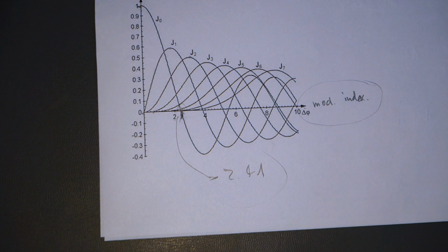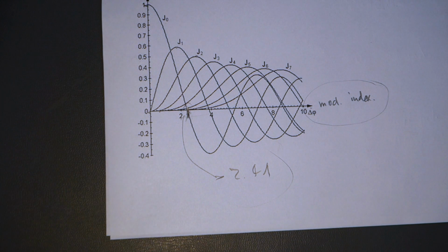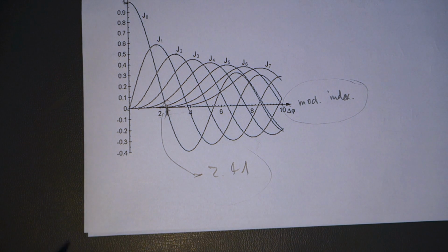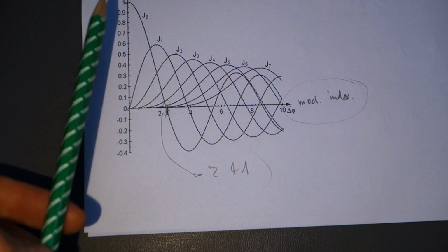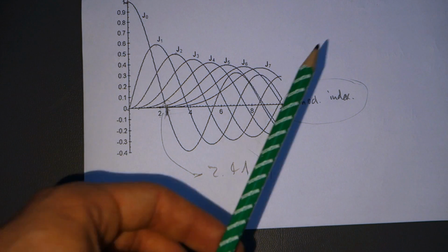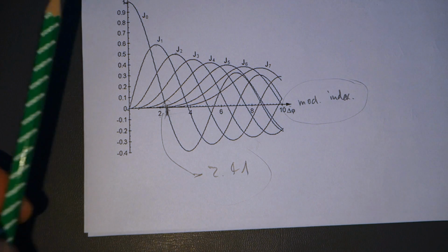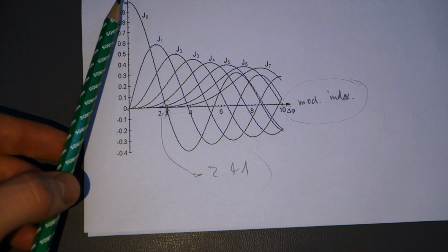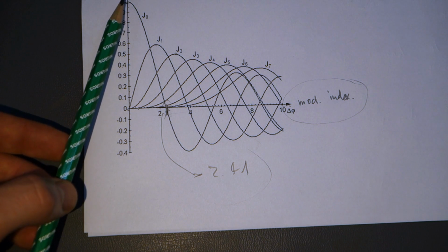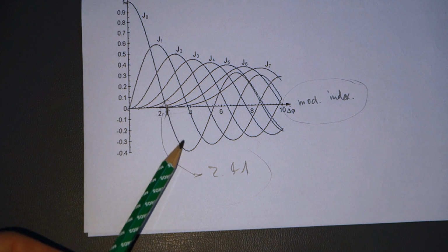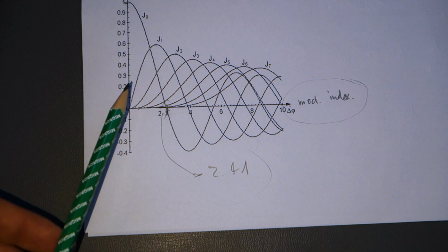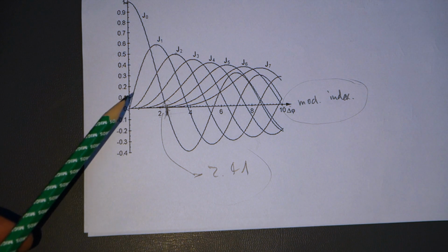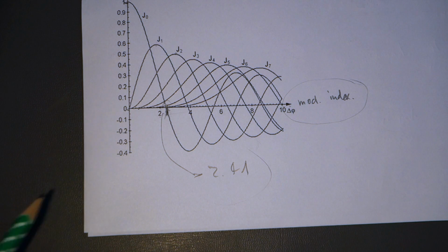Now, there is a complicated mathematical relationship that explains where the sidebands are of an FM modulated signal, and how large they are, what their magnitude is. I'm not going to derive that, so I'll just show you the result. That's a bunch of Bessel functions of the first kind of various orders here. And it turns out that the magnitude of the carrier that we saw in the plot during the experiment corresponds to that first line here. The magnitude of the first pair of sidebands corresponds to that. The magnitude of the second pair of sidebands corresponds to that, and so on.